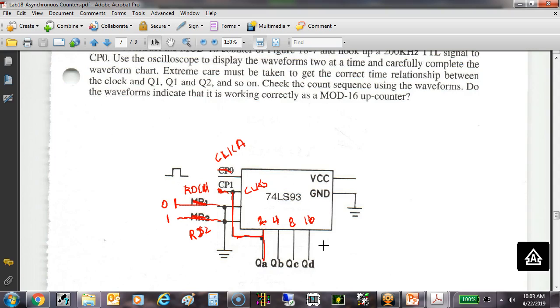And that's something, guys, you're going to run into all the time: people misusing the term ground. It's common on every data sheet, they'll call that pin ground. But it doesn't have to be a ground, right? Calling it ground is okay, just as long as you understand the difference between a common and a ground. But Brian will correct you over there if you call it a ground.